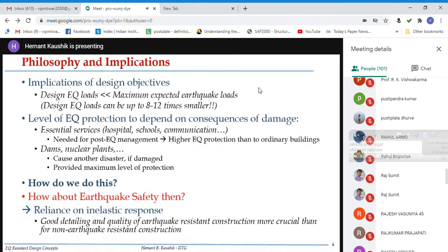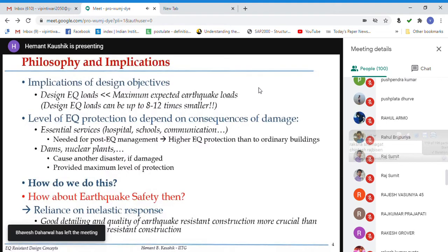So that means that the material has entered into non-linearity. The steel bars may also yield, which is again a non-linear response. So we are not only relying on the linear elastic portion of the material stress-strain curve, right? Hooke's law, we are way beyond that now.